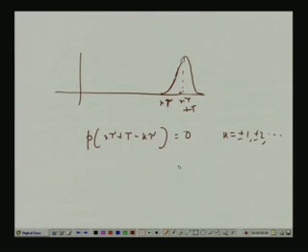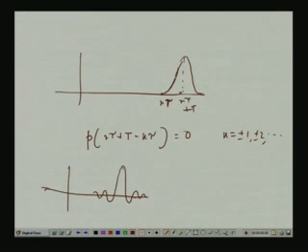Like a Nyquist pulse, this sinc pulse for that matter. The pulse we have shown does not follow this zero forcing condition, but look at this pulse. Suppose this is your center point and this much is tau, this much is tau, like that. As you go to the left by tau or 2 tau or 3 tau, or to the right also by tau, you have a zero crossing. So, this will ensure that there is no intersymbol interference. So, we design such pulses; these pulses are called Nyquist pulses.